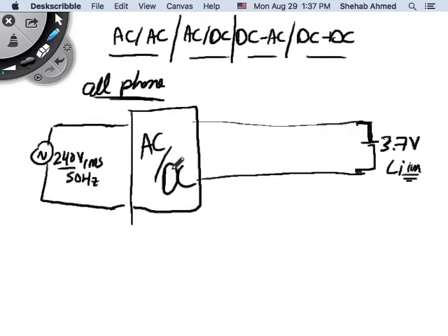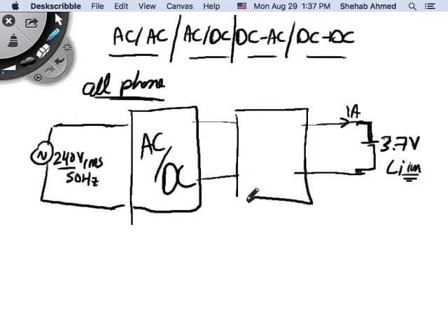Another case is sometimes you may put in here a low-cost AC to DC converter, because you know that after that I need a very controlled current to charge my battery. Typically a low-cost AC to DC converter will not be able to do that. So instead of just using a single stage conversion topology, you would use a series set, where this AC to DC converter provides some DC voltage, lower than 240 volts but much higher than 3.7 volts, probably not controllable because it's cheap.